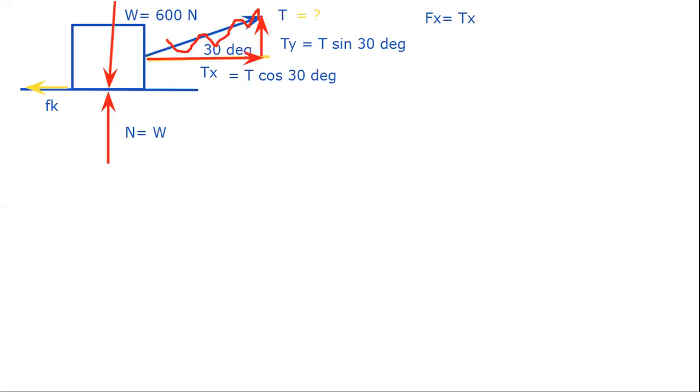And if we complete this equation, we will be subtracting our frictional force here. So minus Fk that goes left. And that's it. There are only two forces horizontally. Now, if this one is moving in uniform motion, then they will have a total value equal to 0. So from this, we see that Tx is simply equivalent to Fk. So this is one equation, horizontal forces. Now, vertical forces on the other